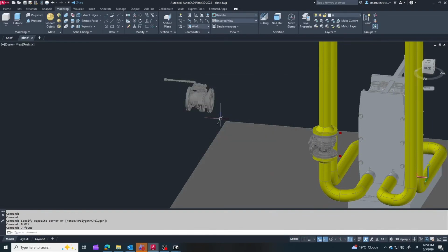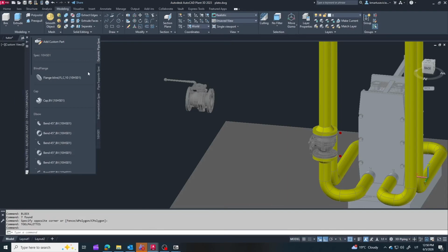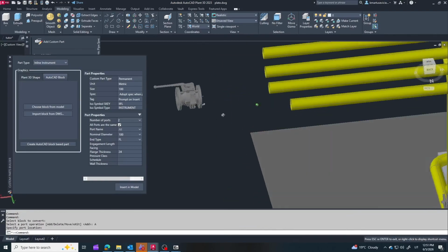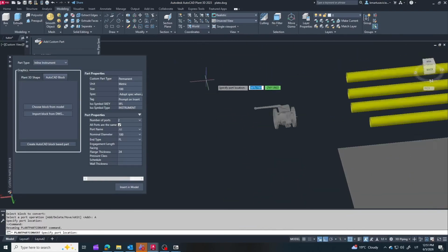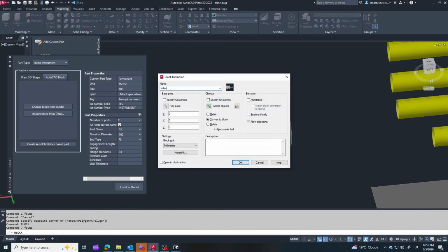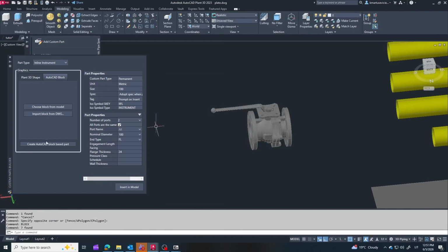I selected a manual, full-bore ball valve operated with an L-shaped lever, and now I'm converting it into a live plant 3D component to place on our lines. If you look closely at the first valve I dropped in, I noticed the model didn't include the lever geometry. To make sure the installation is completely practical and maintenance-friendly, I decided to switch it up and use a fully ended union connection here. It's a much cleaner choice for these compact lines.